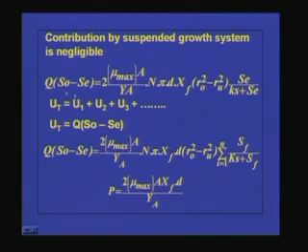So if you want to find out the BOD removed, that is equal to Q into S naught minus Sc, which will be equal to 2 into mu max into area by Ya into N into pi into D xf R naught squared minus Ru squared into Sc by Ks plus Sc, and you know that this Sc is very negligible. So you will be getting the equation like this, and we can replace this entire term with a constant P, which is equal to 2 into mu max A into xf into D by Ya. This will depend upon the rotating biofilter, and this will be a parameter decided by the system.